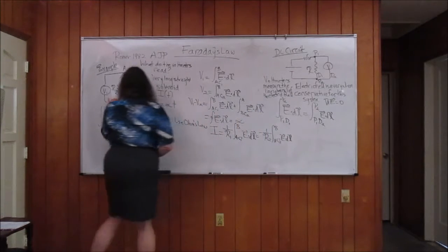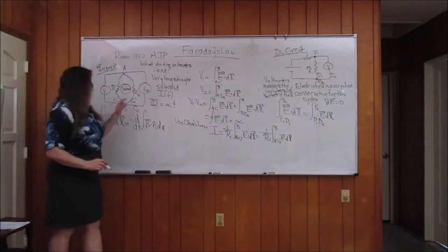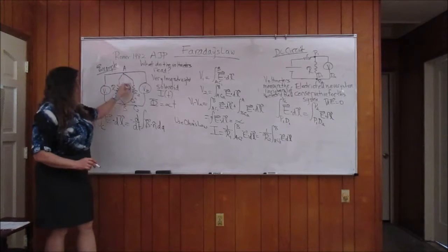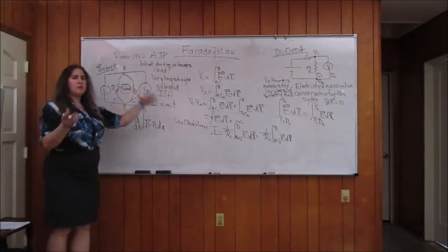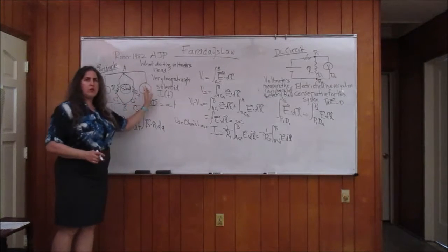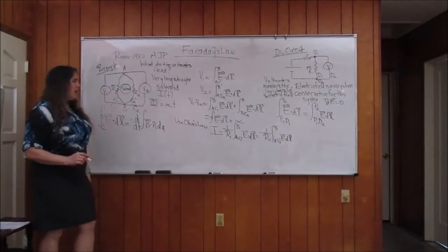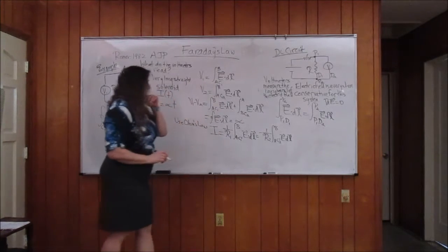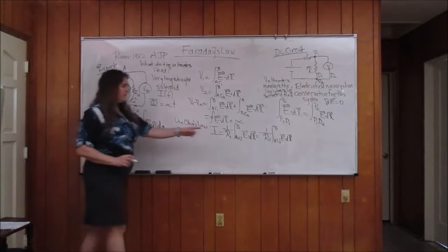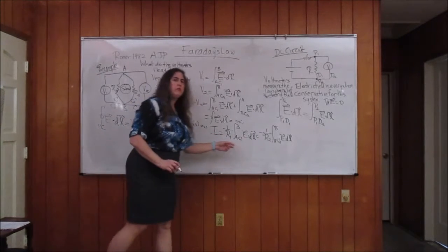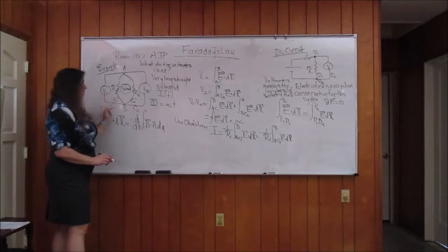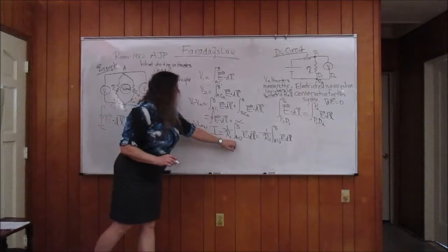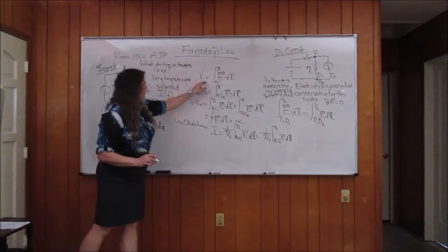You see, we're assuming here that the voltmeters draw very little current, so our current is basically continuous through here. So there's a negligible amount of error by ignoring any current that's drawn by these voltmeters. We're assuming that they're very high impedance. Okay, so comparing this with this, we're not quite there yet because this integral is taken along the path C1 prime, not C1. So how do we justify using this down here?